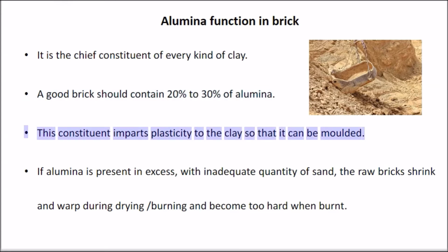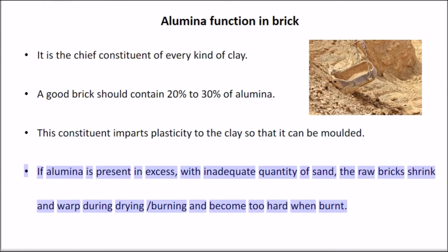This constituent imparts plasticity to the clay so that it can be molded. If alumina is present in excess, with inadequate quantity of sand, the raw bricks shrink and warp during drying and burning, and become too hard when burnt.